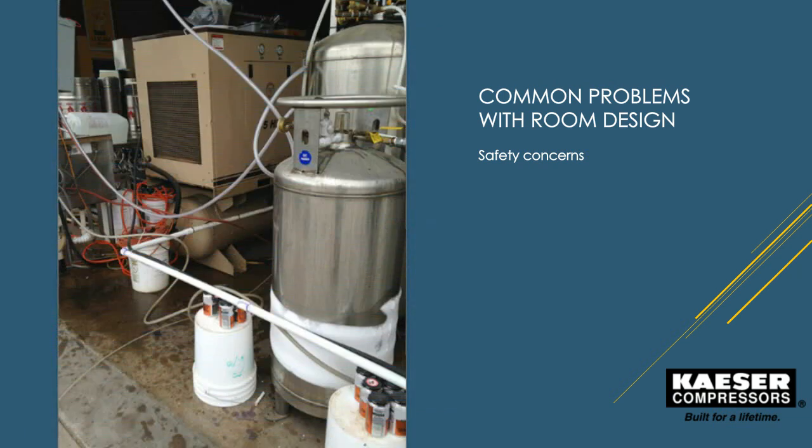Further in that safety topic, this is on, let's say, dry land, not in the air. This compressor has the piping coming out, and that piping is resting on an upside-down bucket and cans. The piping's not supported at all either. Plus, the piping is PVC, which is a safety violation. PVC and compressed air don't mix. OSHA has come down and provided guidance on that, so incompatibility. Those are two significant safety issues that I would be concerned with.